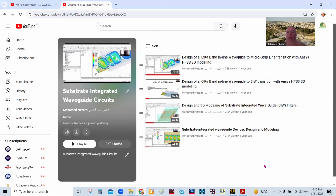Since the height of the waveguide, the B variable, is in this case the substrate height, we still can operate with a TE10 mode and produce PCB implementation of a waveguide. I have produced 4 videos already on the concept of substrate integrated waveguides. You can refer back to them. These are in my channel.